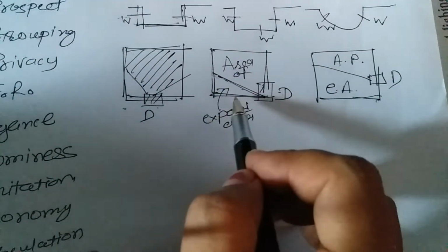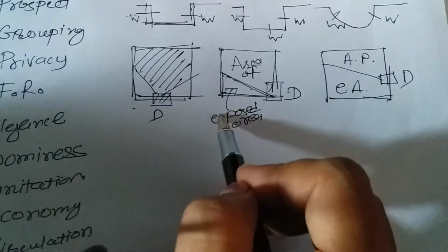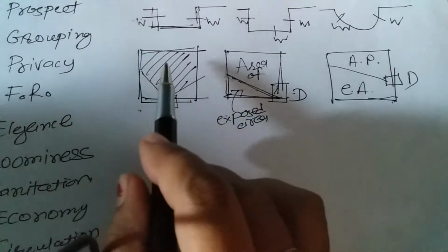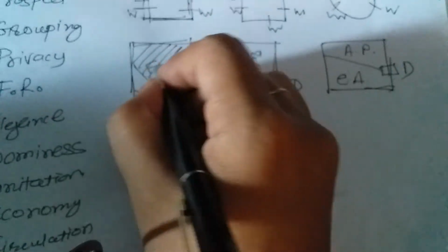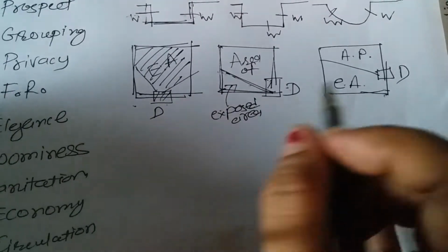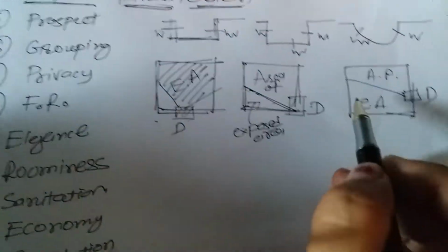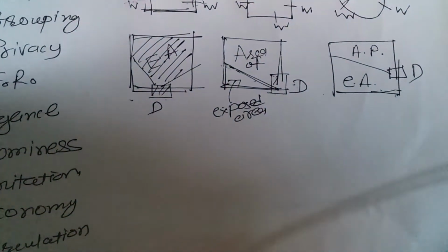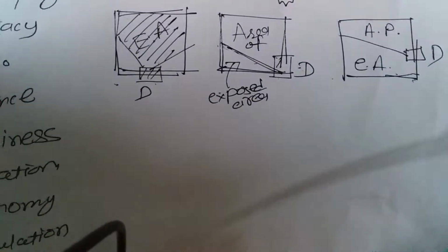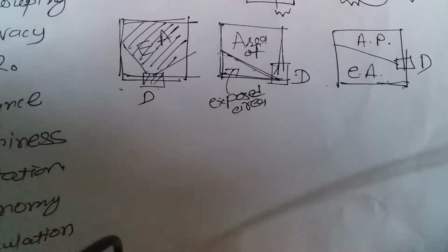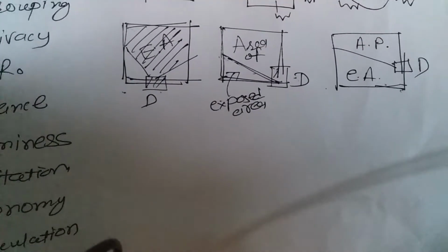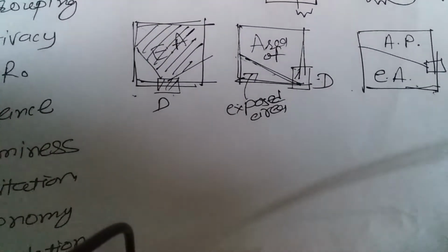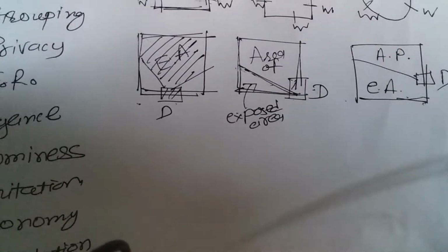While selecting a door, if I select this corner, exposed area is less and area of privacy is maximum. If we choose the door in the center, then exposed area is maximum and area of privacy is less. If I select a door in this type of position, exposed area and area of privacy are both equal. So a large portion of the details of any room should not be visible at a glance. For maximum privacy, single shutters are better than double shutters. Provision of frosted glass for windows provides more privacy than plain glass. Louvers for shutters provide ventilation as well as privacy.